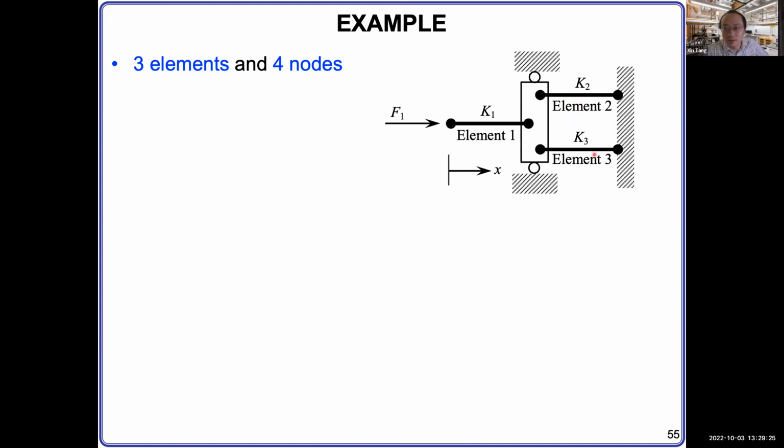In that case, rigid material sustains more force, because it is more capable. Soft material sustains less force, because here you want to keep the deformation of these 2 the same. So if the deformation is the same, then the soft one has less force. The hard one has more force, right? So that's the reason. So don't assume that if the geometry or deformation is the same, then the force is the same. It's not always the same. Okay? We need to specifically solve the problem to find out.